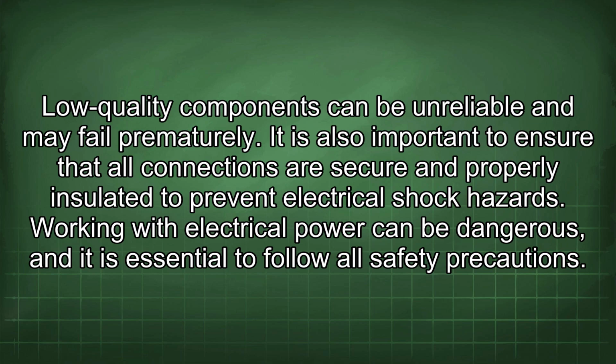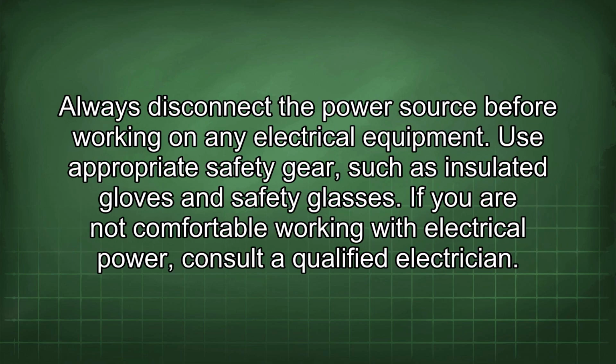It is also important to ensure that all connections are secure and properly insulated to prevent electrical shock hazards. Working with electrical power can be dangerous, and it is essential to follow all safety precautions. Always disconnect the power source before working on any electrical equipment. Use appropriate safety gear such as insulated gloves and safety glasses.